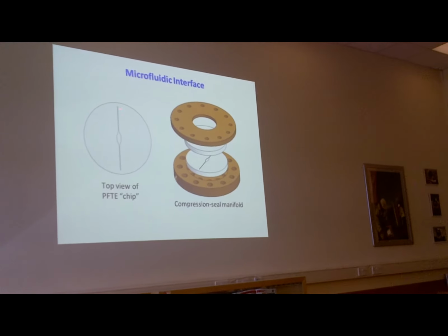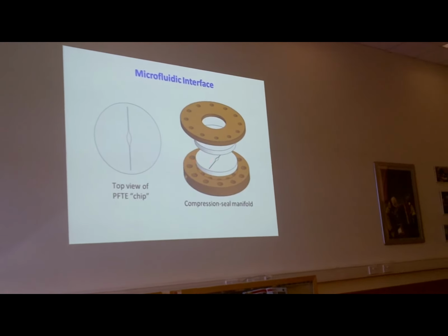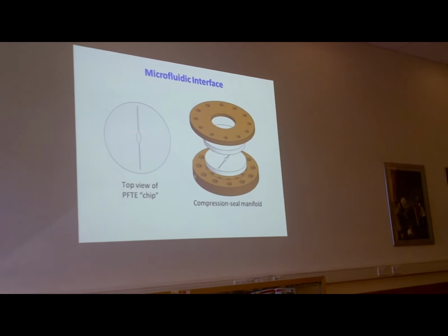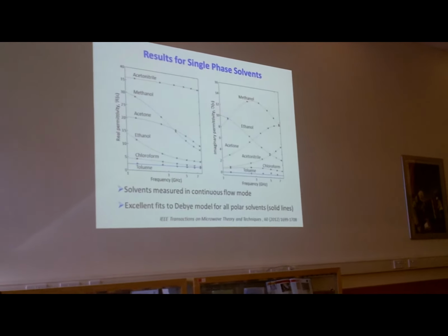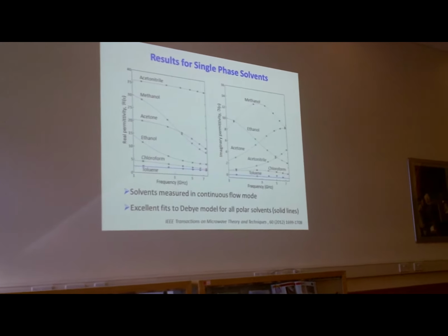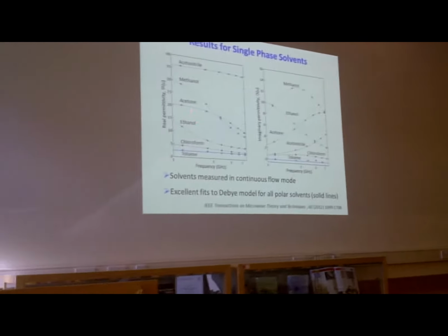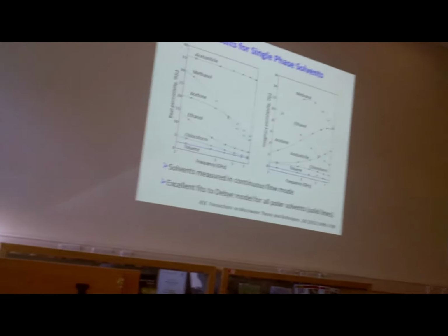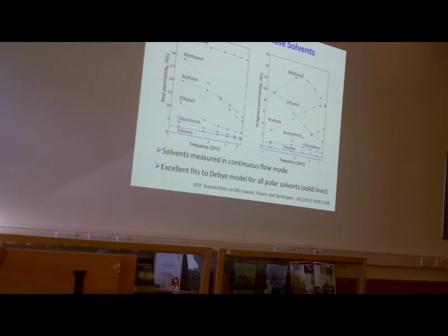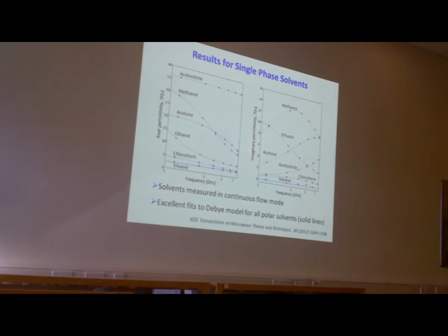This is what happens. The red curve there is when the resonator is just sitting in air. And the blue curve is what we get when the resonator is dipped into a liquid. So you can measure the dielectric property of that liquid at all these different frequencies, and hence you open up the dielectric spectrum of that liquid, which again allows you to have nice fingerprinting of that particular liquid.